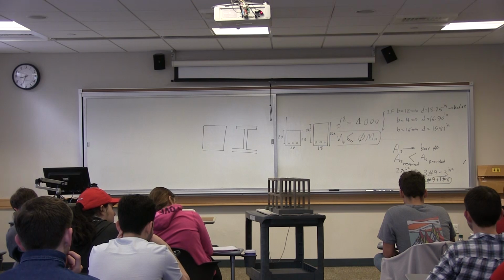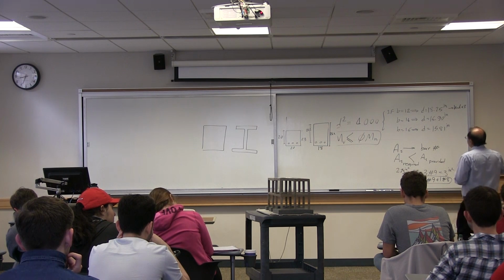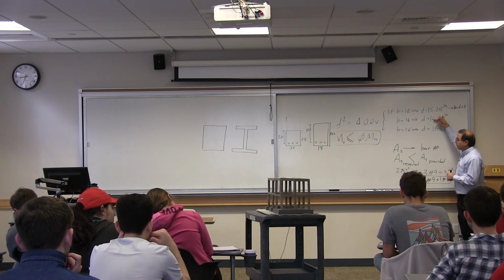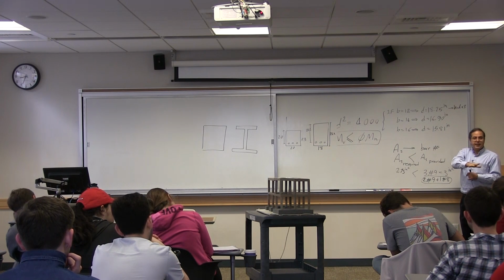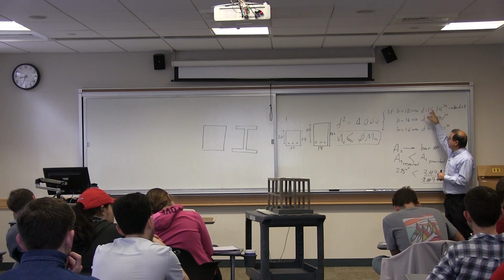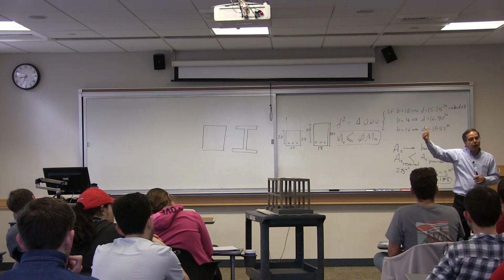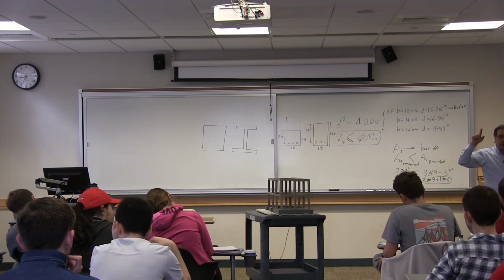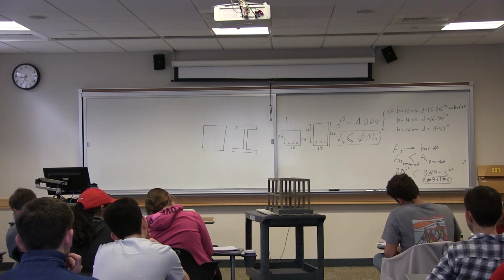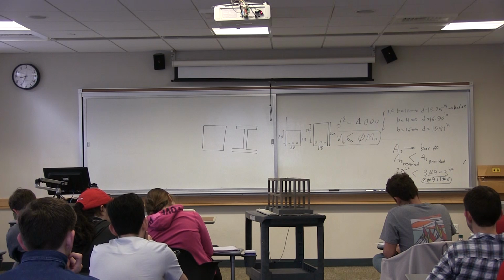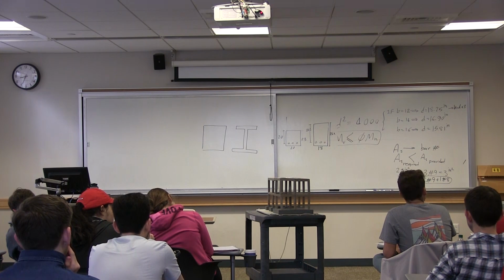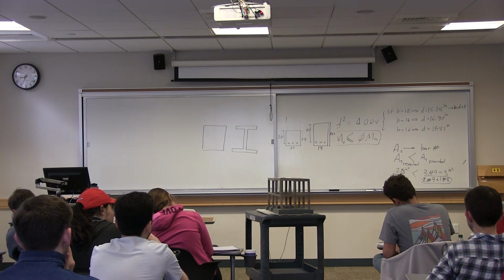So at this time, if I wanted to choose one of these and I don't have any other requirement, I perhaps would go with the first one, with the same logic I mentioned, which is not really correct but is a reasonable point to make at this time: that a D over B of about 1.5 is better than the other numbers that are less than 1.5.